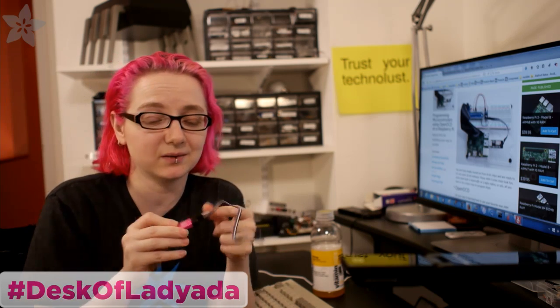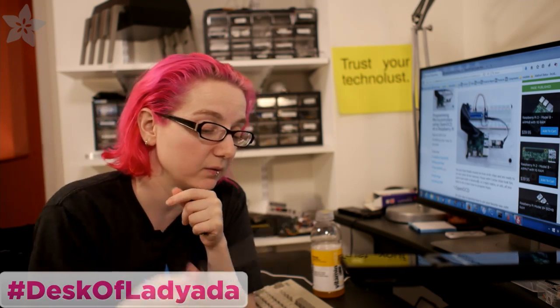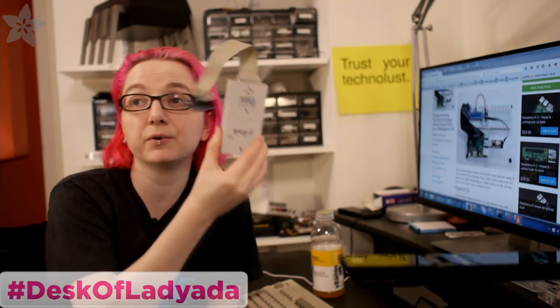The only thing is once in a while, these get into a weird spot, which I seriously don't understand. It will not be able to verify, and I actually have to unplug it, wait a minute, and then plug it in and then it starts working. I don't know what the deal is, but they're $5. So as long as you're not programming hundreds, you can probably get away with just using an ST-Link. It's 3-volt logic, which is kind of nice. You don't have to feed the logic in. So these are the two options that we use now. I use the J-Link for development, and then when we go into production, we use the ST-Link.